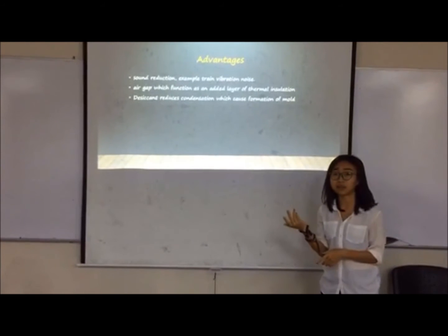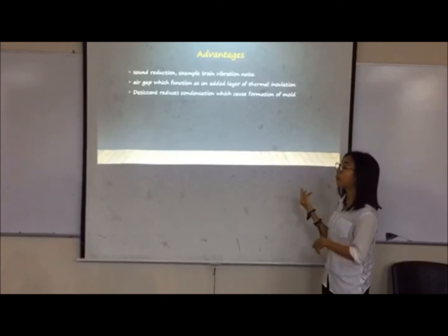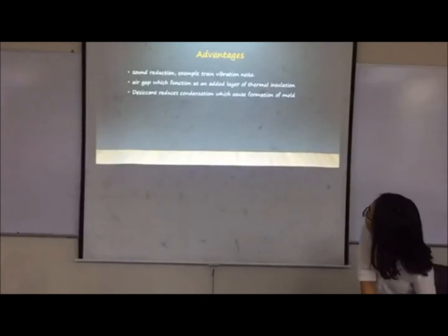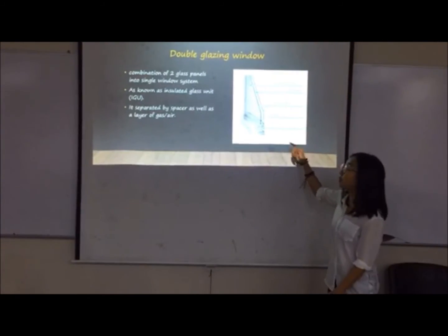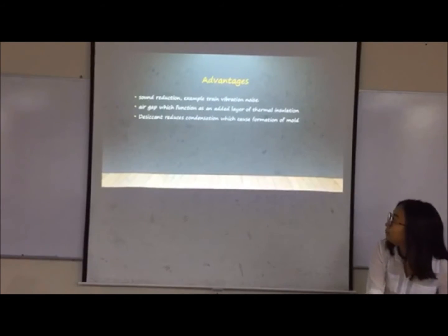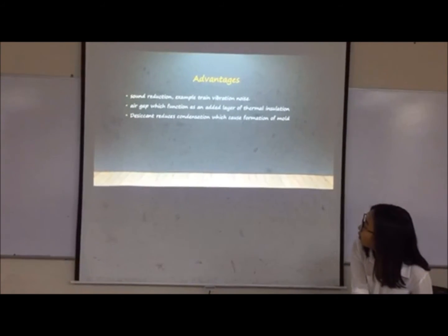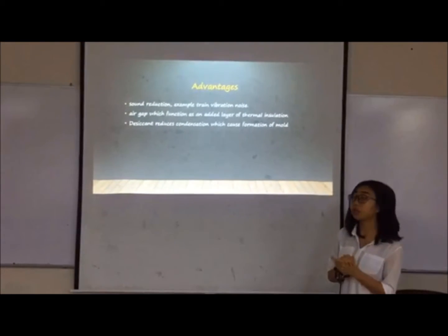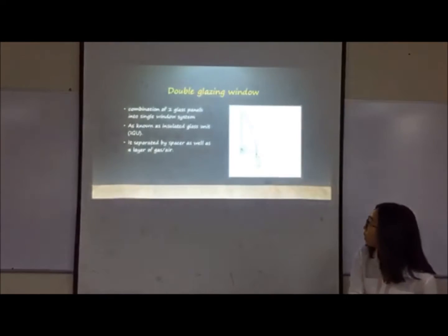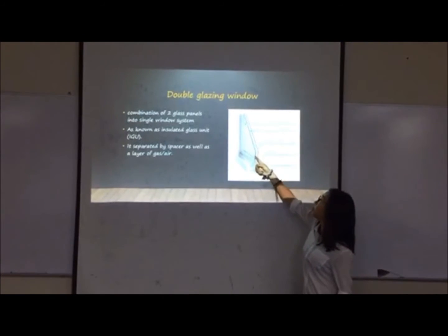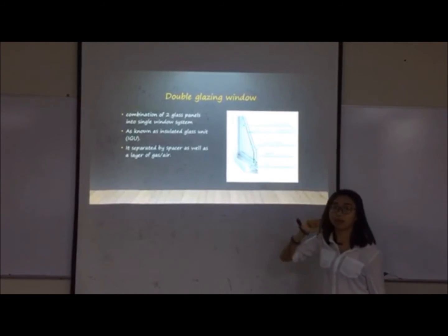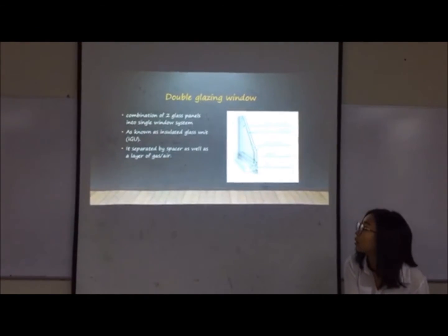As I said just now, the gap will be filled with argon gas inside. And then the desiccant will reduce the condensation, which causes the formation of molds. The desiccant will be put inside the spacer and then prevent the molds from occurring.